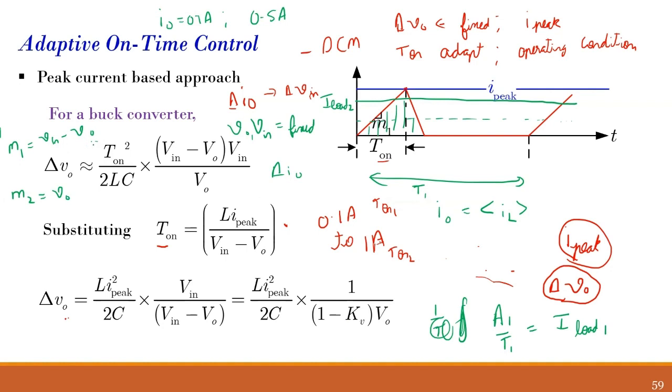But then the closed loop will operate to regulate your output voltage to remain fixed. That we are not showing over here. We are now discussing the steady state. In your steady state, your V in is fixed and your output has also reached its steady state regulated value of 1 volt, assume. So this slope will remain the same.